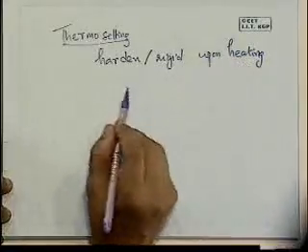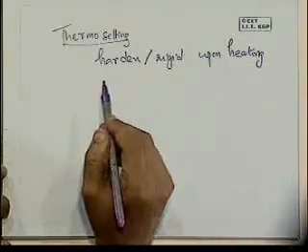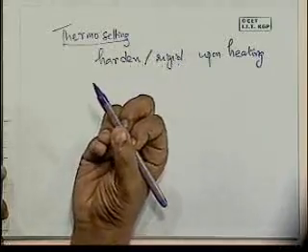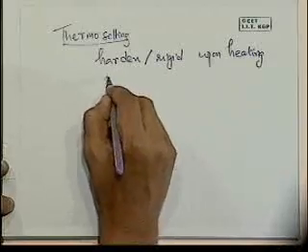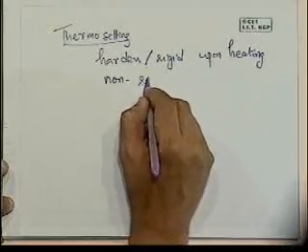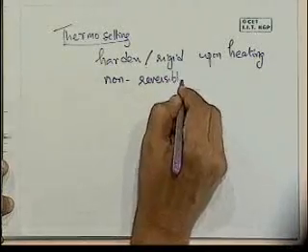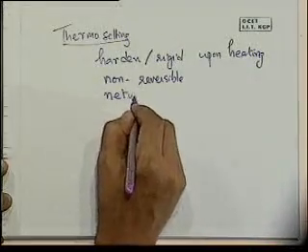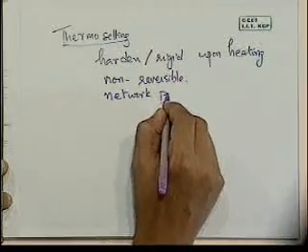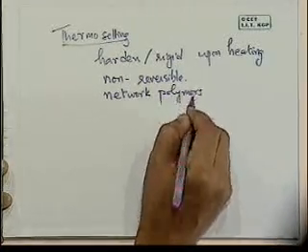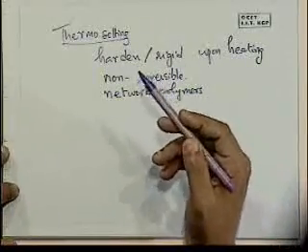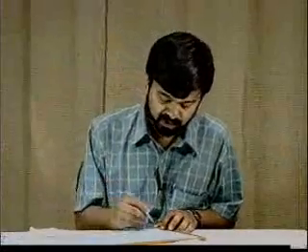And there are similar ideas involved there. Bonds are being created during the heating process that causes the material to become far more rigid than it was. It's a non-reversible process. And this is a characteristic of network polymers. Okay. The previous case, thermoplastic, we saw was a characteristic of linear polymers. This is a characteristic of network polymers.